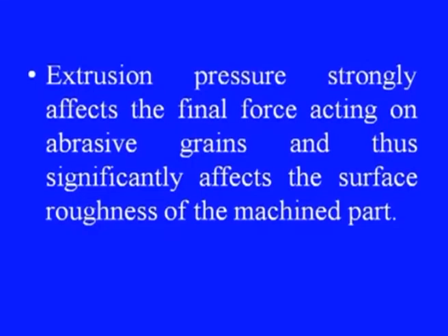Extrusion pressure strongly affects the final force acting on abrasive grains and thus significantly affects the surface roughness of the machined part.